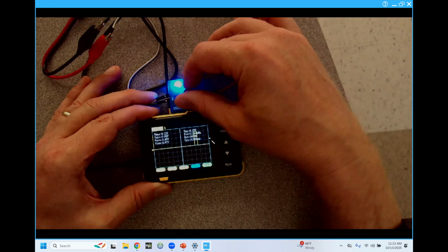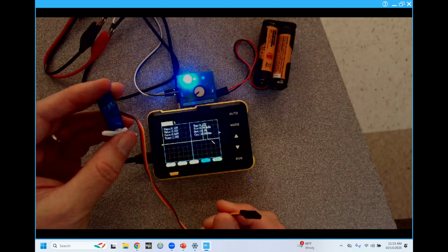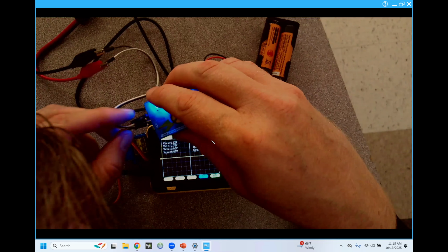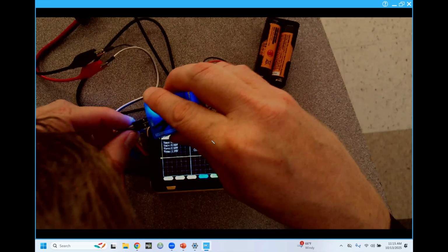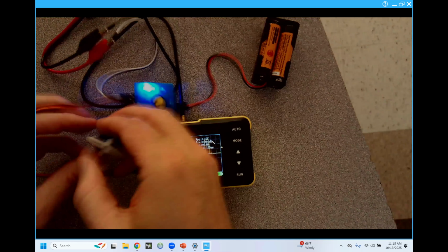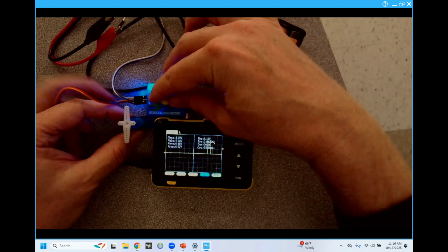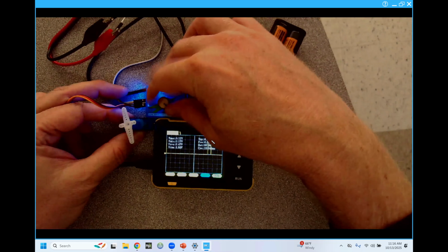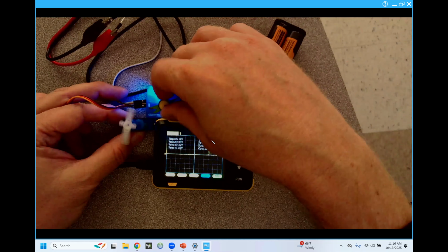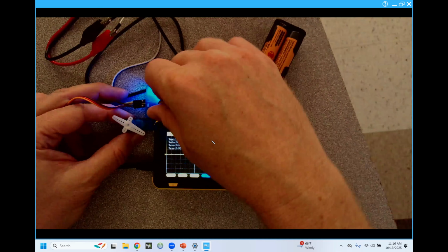Okay. All right. So now I'm going to take a servo and plug it in. The servo is a device that moves its position depending on the pulse width modulation it gets in. So you can see as I turn the knob, the servo turns. So that's a really convenient servo. That's why it's called a servo tester, because you're just giving different pulse width modulation out. So the servo responds to the PWM signal.